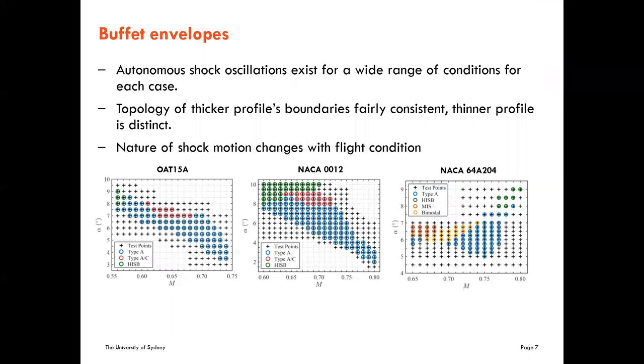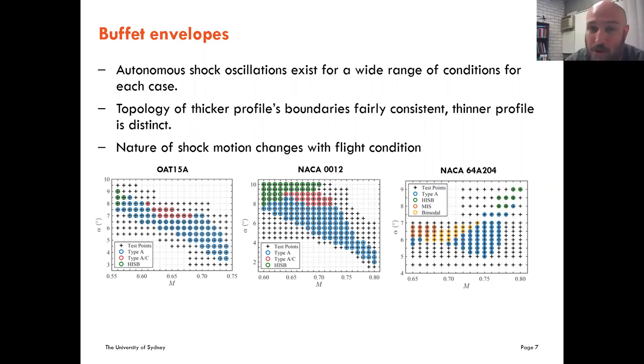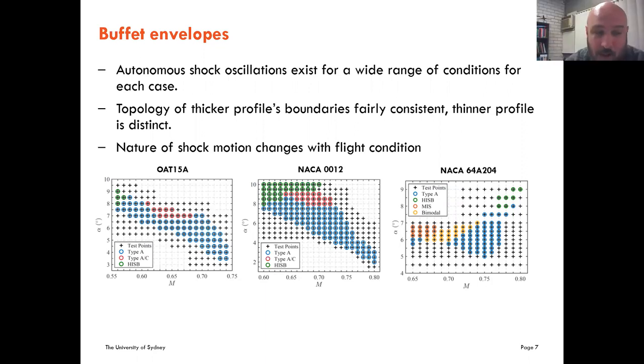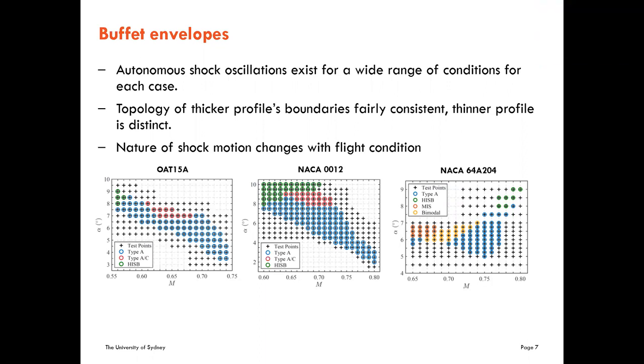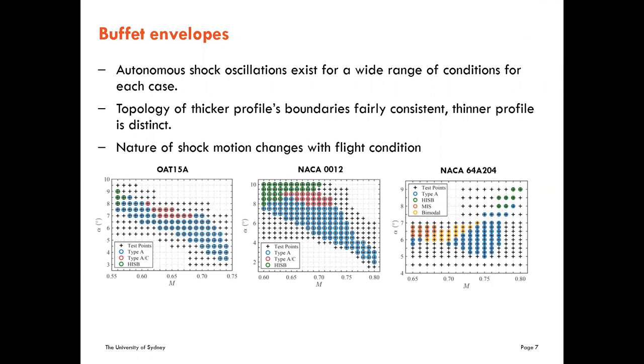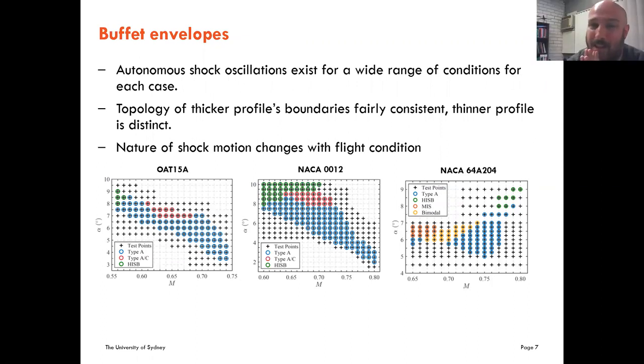And what turbulence model have you used here? We actually looked at almost all of them to see which one works best. Generally, the SST model does very well, and the Reynolds stress model as well. The others are really not very good. But saying that, you will also need to change whether you use a pressure-based or a density-based solver to actually get it to work. And there is no understanding of why that is and which one to use under which condition.